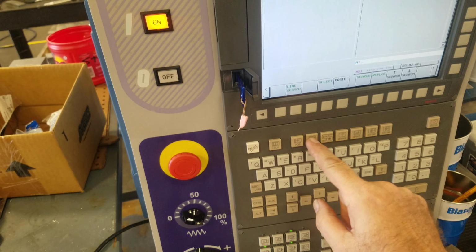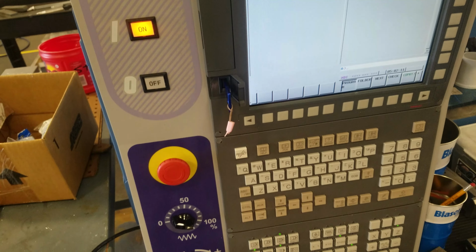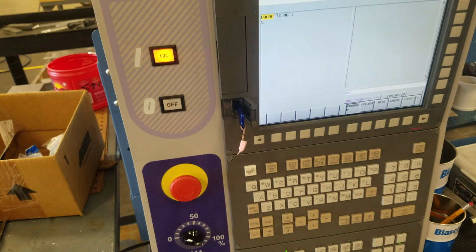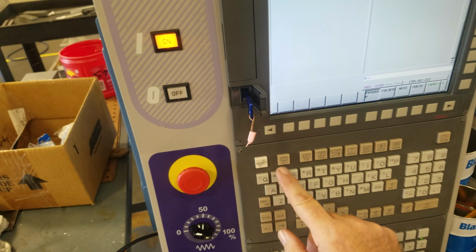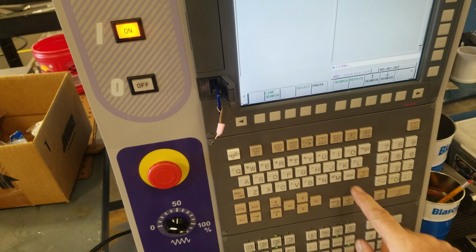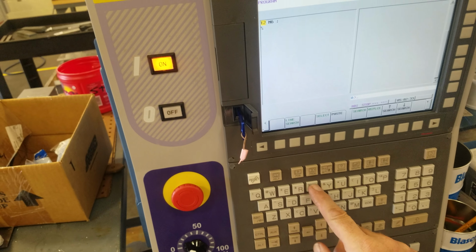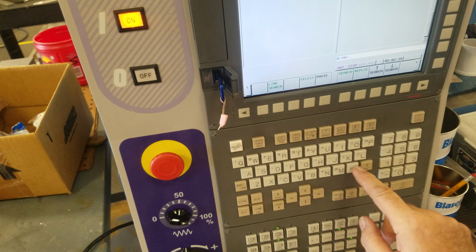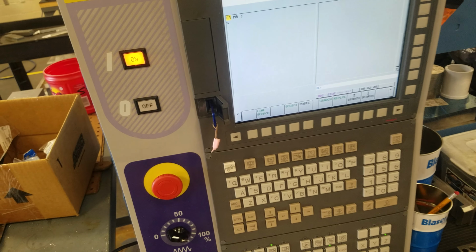So now if I go back to program, oh, wrong one. MDI screen, program. Here's our program. Just do cycle start, and that changes the tools. So you can load all the tools in one by one, and then go to the next one. Just hit reset. We'll type in T2 M6 end of block input, cycle start, and that changes. T3, alter, put an M6 in there, end of block input, cycle start again. You can keep on loading tools like that.